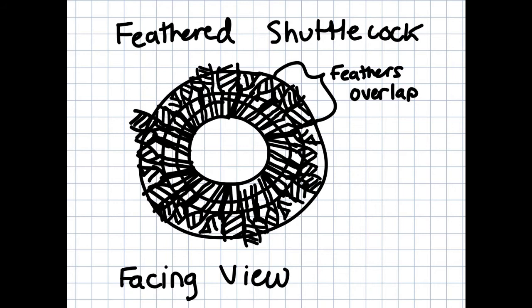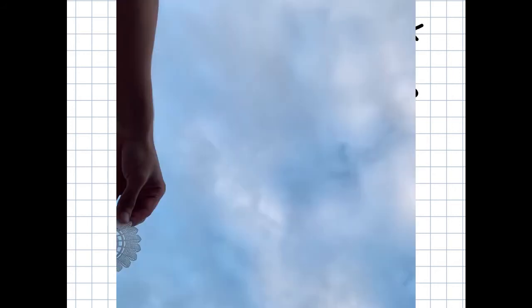Well, the shuttlecock rotates due to the arrangement of feathers on the cork. The slight angle the feathers form with each other, as well as the geometry of the feathers, induce a moment around the center of the shuttlecock. In addition, the relatively high density of the cork, compared to the feathers, forces the shuttlecock to move towards its most stable configuration, which is leading with the cork. This is shown by the rapid speed at which the shuttlecock turns around after being hit. It takes an average of 20 milliseconds to turn around and 80 milliseconds to stabilize while in midair.